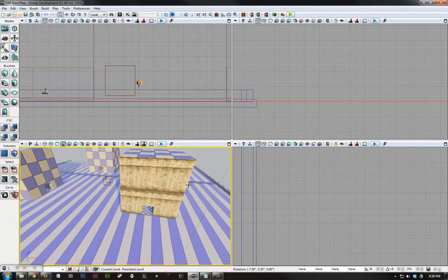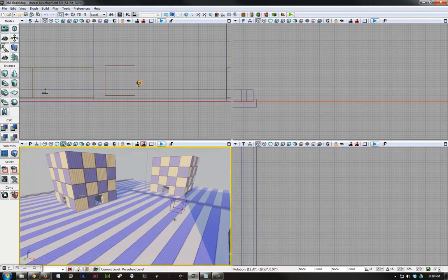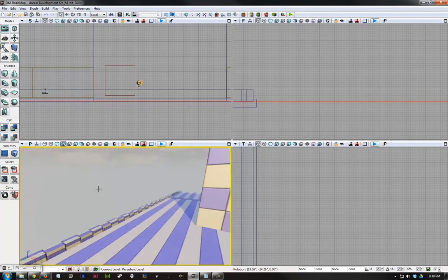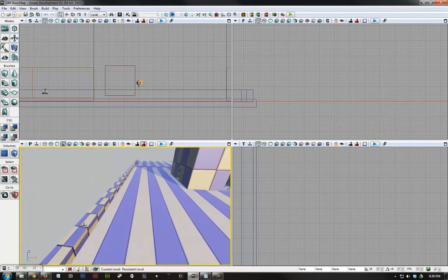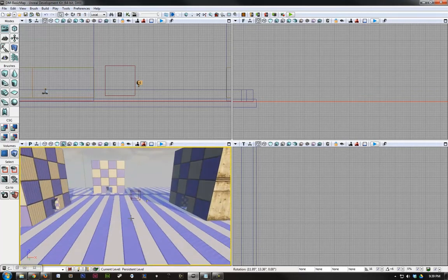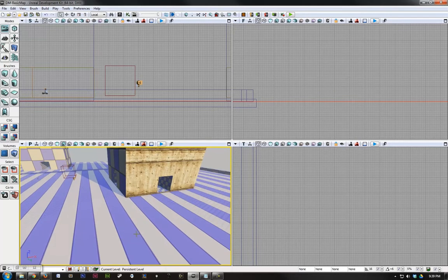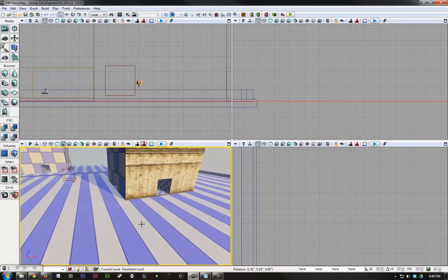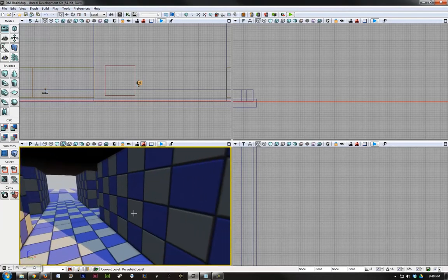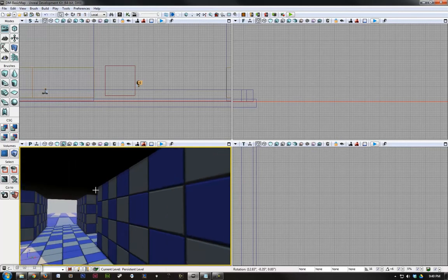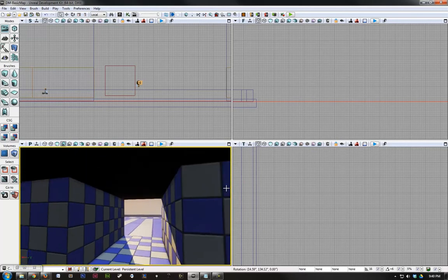So now getting back to our floor piece here, which has this stretched out pattern, we can also note that all the BSP areas we have are of different checker sizes and shapes. Now the checker sizes are going to dictate how your material is applied to that particular piece of BSP. And so traditionally what you want is nice square patterns like this on our insides here.